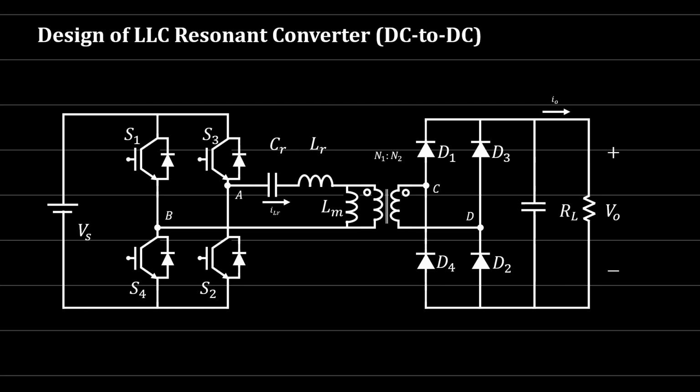It is called an LLC resonant converter because we have two inductors. One is the resonant tank inductor and the other one is the transformer inductor, or the coupled inductor value, which is the magnetizing inductance. We have the L and C resonant tank, and also the inductance from the transformer, the coupled inductor. Again, our aim here is to make sure that we have the maximum power or the maximum gain from the combination of these components.